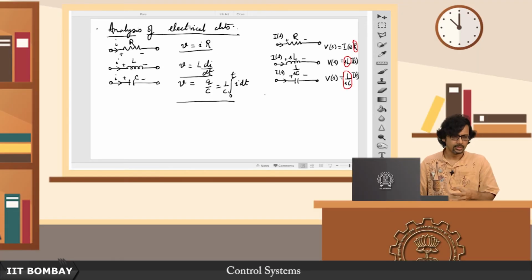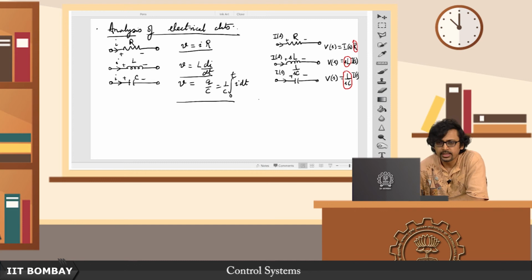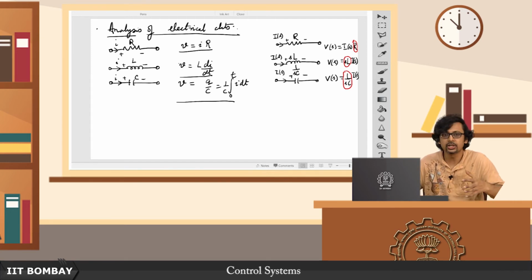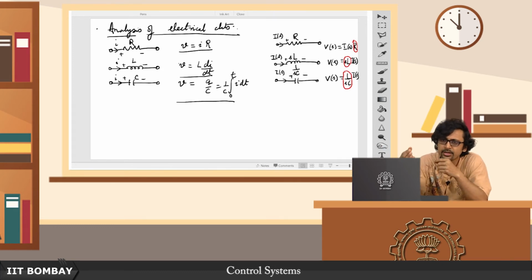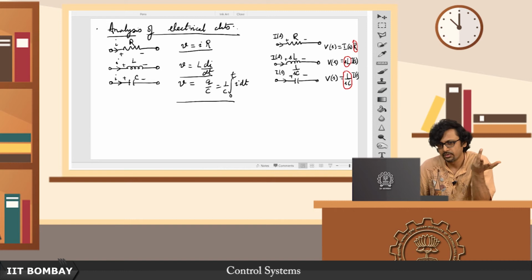Alright. So now, having seen all of this, we are claiming that we no longer need to look at the time domain differential equations in an RLC circuit with a combination of different resistances, inductors and capacitors strewn throughout the circuit. All we are going to do is replace every inductor with SL, every resistor of course with the R that it already had in the time domain, and every capacitor with 1 over SC.